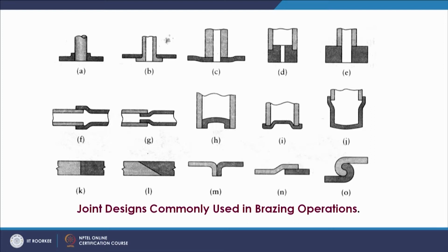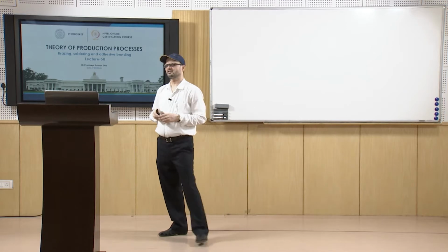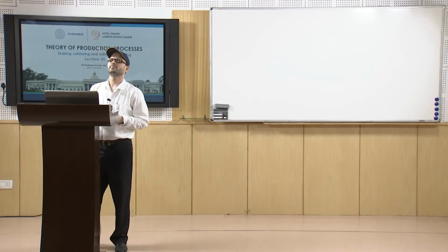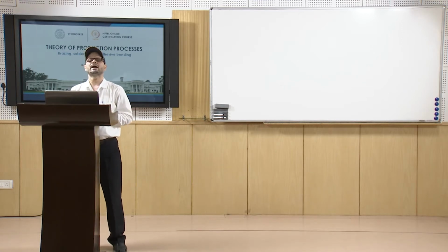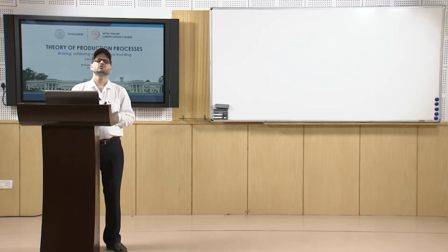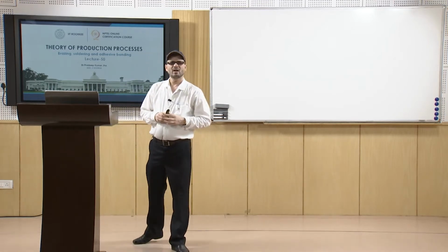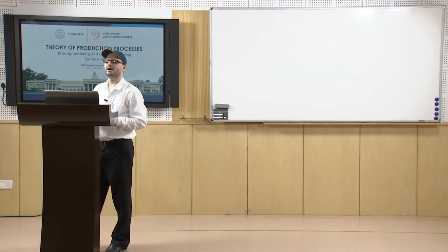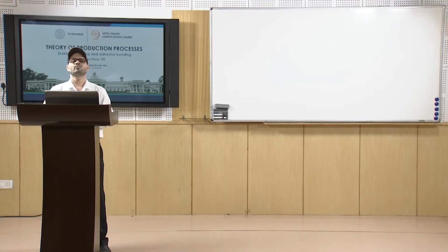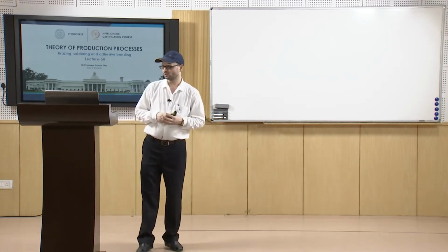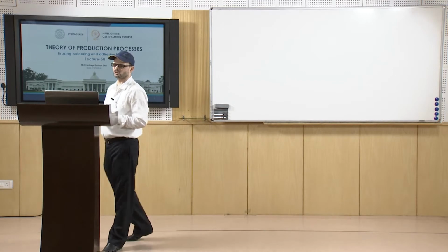Now, we will discuss another process, that is soldering. As we discussed, in the case of soldering, the filler material will be melting below 450 degree centigrade. So, again here also the joint is filled by the capillary action, and here you have the different sources of soldering, that is soldering iron, torches or ovens. So, based on that you will have different soldering methods, and it is used to join various metals and parts thickness.